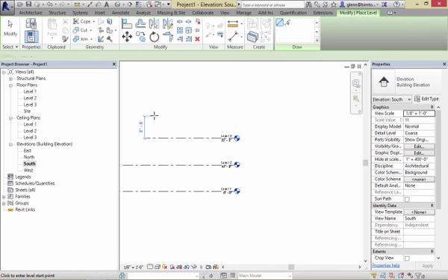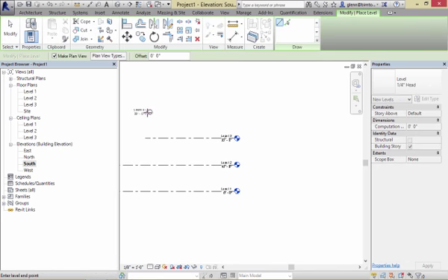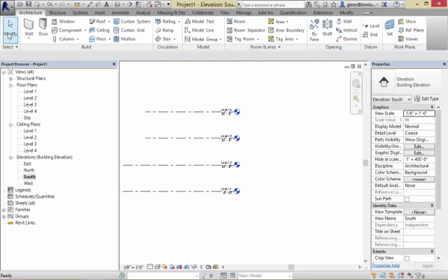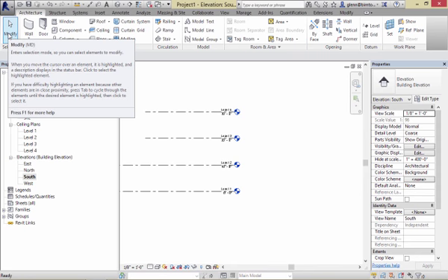And I can go through and draw level 4. I'll say 10 feet above that. I'll have level 4. Okay. And I keep on drawing them. Okay, and that actually works out just fine. So try drawing a level, see if you get another level in there. Again, you come to a section view, use the level tool and draw it out.